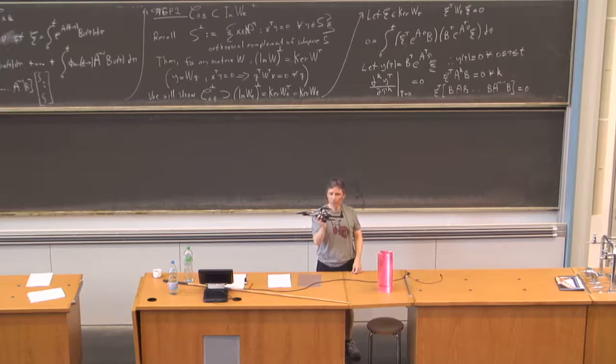If you want to roll the device, if I call this the x-axis, I forgot to mention one important thing. These 2 propellers spin in one direction, and these other 2 propellers spin in the other. These pitches have different orientations. These are clockwise propellers, these are counterclockwise, but they're all producing thrust going up.